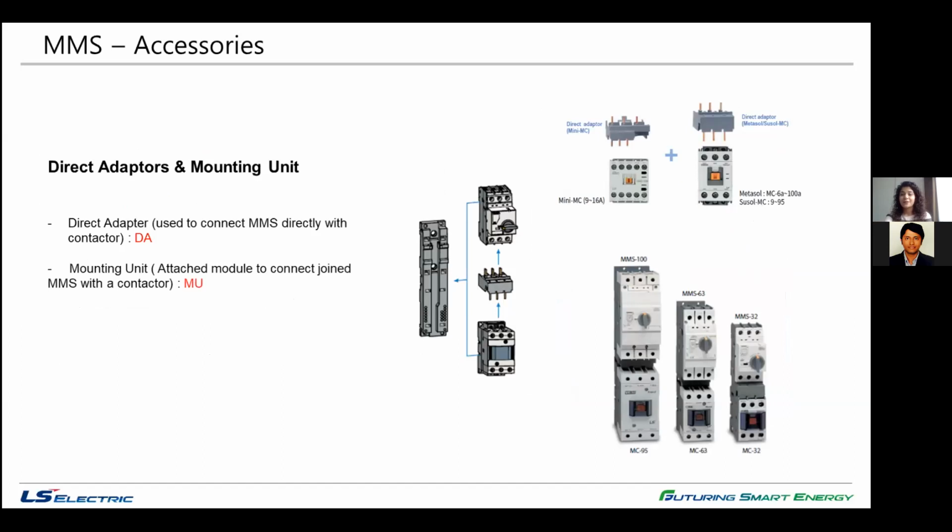Lastly, talking about the direct adapters. As I mentioned before, in the MetaSOL contactors, we have direct adapters and mounting unit. If you want to directly connect an MMS with the MetaSOL contactors or with the mini contactors, you can go for a direct adapter. If you want a separate mounting unit, you can go for the mounting unit. You can attach the module to connect the MMS with the contactor or with the mini contactor. So that was a brief on all the 3 components.